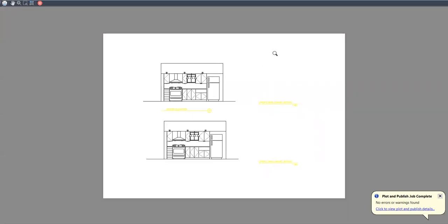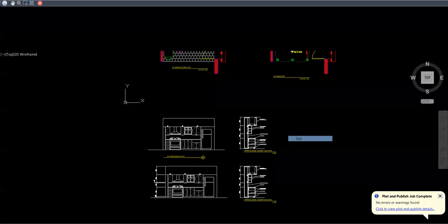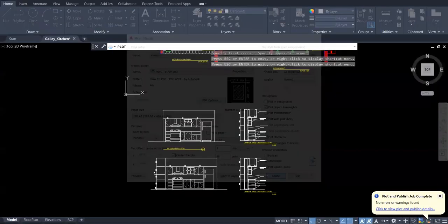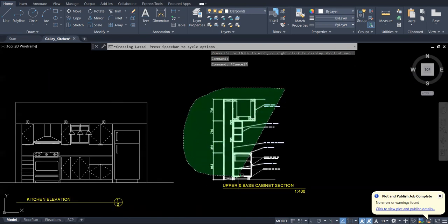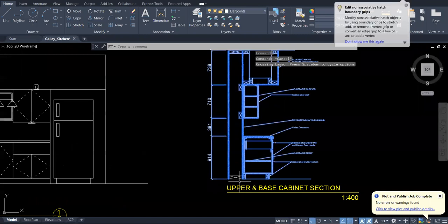Okay, probably because we have a lot of things here on that side, which is the elevation, I put that in a different layer, so it's not showing, but yours is going to be showing because all of your layers are proper. I didn't properly add the detail to the proper layers. Okay, so this is basically how all your elevations are going to be coming on the same sheet according to the size, because this time, if we're printing a lot of things, let me just put that into the proper layer. Okay, this is 0. Let me put this in layer 0 so it will show. Not default pointer, not going to show by any means.